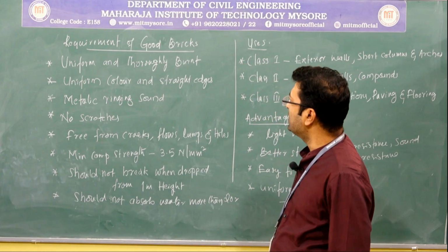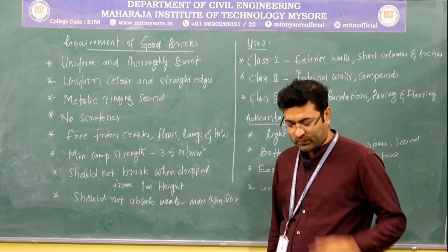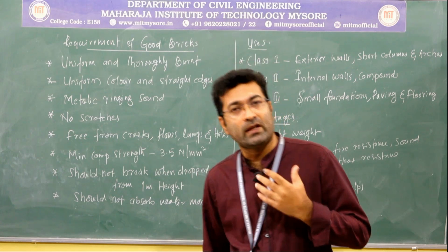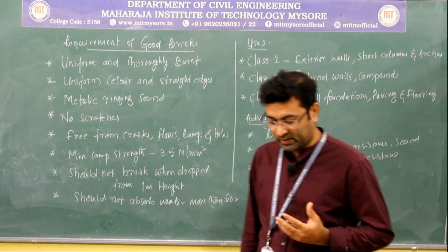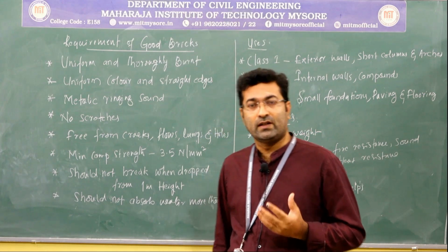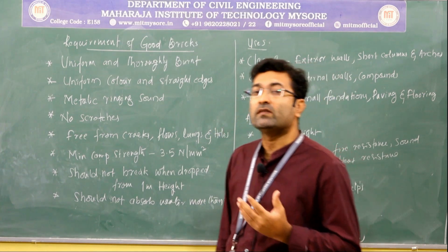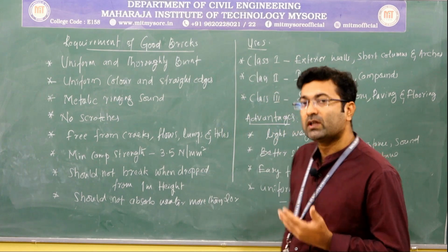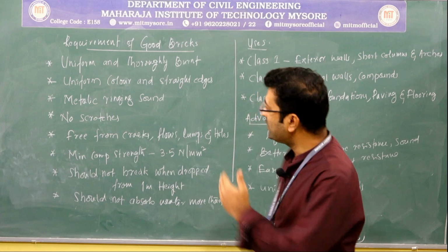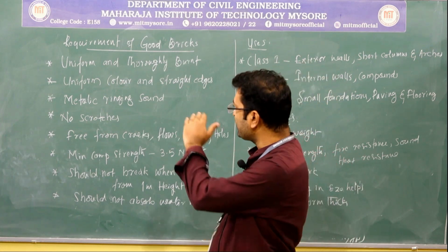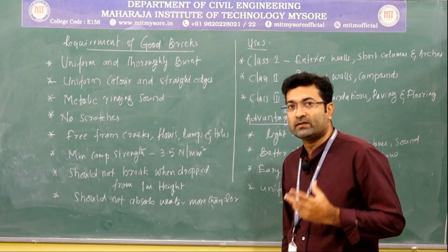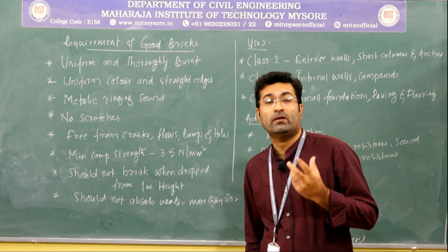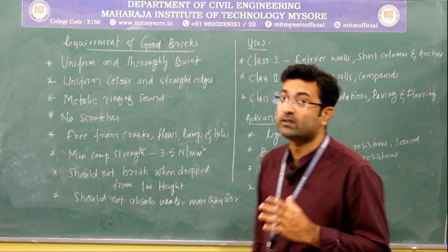Now, we will talk about the requirements of good bricks. Whenever we are planning to use bricks in construction activity, before deciding or before using those bricks, we need to check the quality of the bricks. Whenever we are checking the quality, we need to go through some important points, like the bricks should be burnt uniformly and thoroughly.